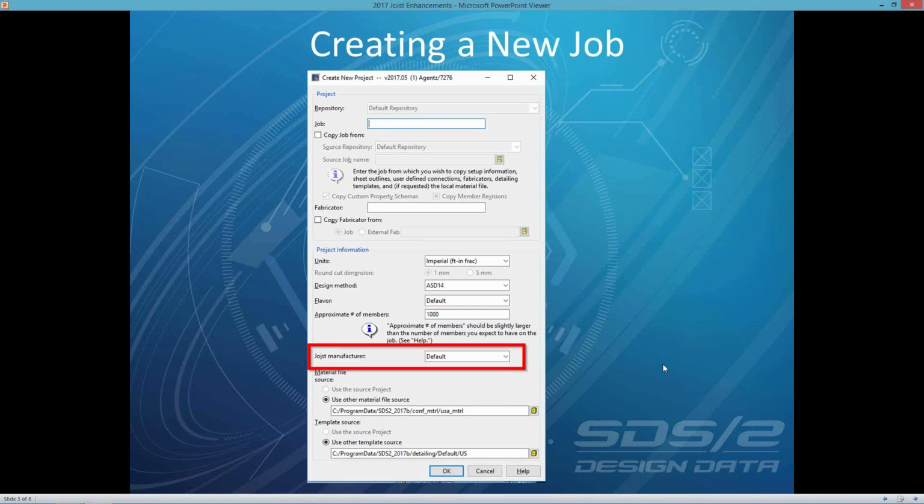So for joists now, they are added at bearing elevation, regardless of the bearing chord. This helps ensure that node matching detects the correct support every time. Users can set different bearing conditions on each end of the joist within the member edit screen.